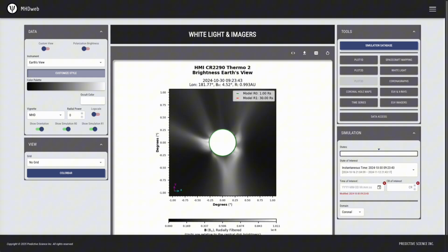And speaking of domain limits, a certain validation error that pops up is the incorrect domain for current view, which you will see over in the simulation widget. This error is indicating that the field of view contains no values that fall within the current run domain. It's sometimes not immediately apparent if a field of view falls within the run domain, considering that the degrees of line of sight is a function of radial distance.